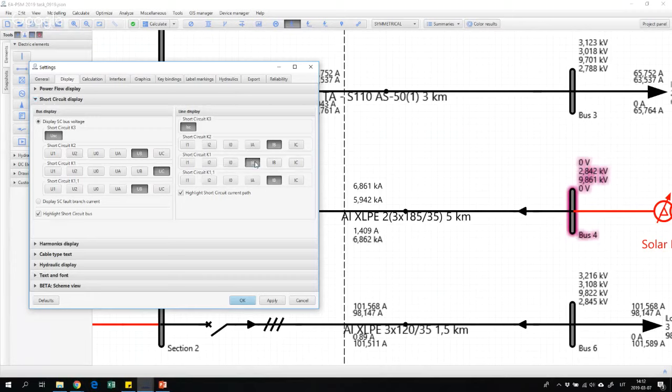However, for example, if we want to check short circuit current in A phase, yes, so we can see that in A phase, this short circuit current will be much bigger. It's 25 amps, because in software we assume that short circuit is going on in A phase if it is one phase short circuit. So all the capacitive currents from the network will go to this particular phase.